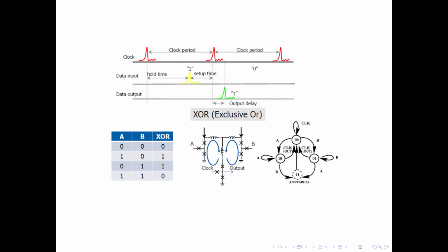Actually, you can have a very similar clock speed. The clock speed in superconducting electronics will be in the range of 100 gigahertz, but the difference from semiconductor technology is that there will be very low power dissipation. A superconducting microprocessor can, in a sense, waste only 1 milliwatt of power. But this has to be paid for at the price of keeping it at low temperatures, usually around 10 Kelvin in niobium or niobium nitride.